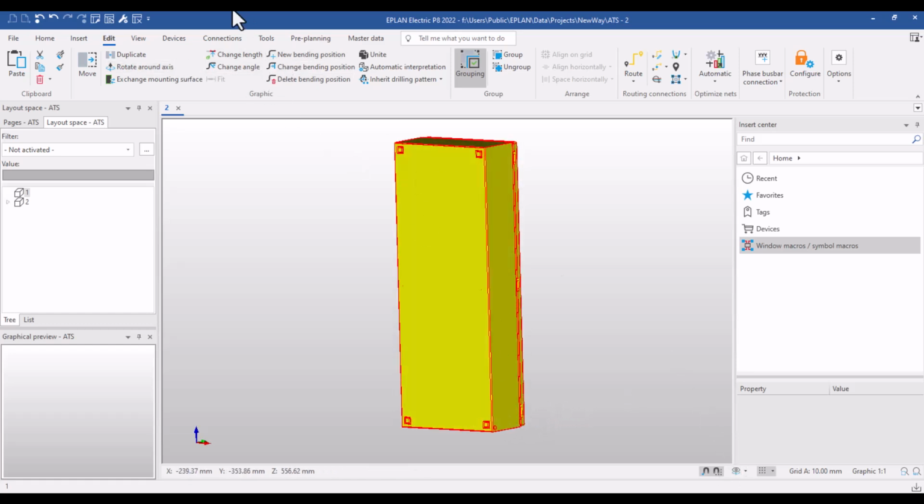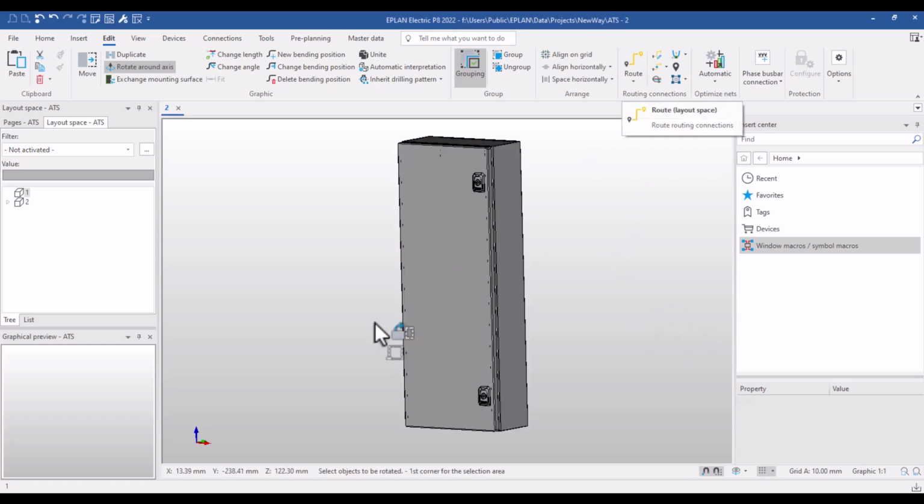After that, I will need to press rotate, select the axis we will need to rotate around. After that, specify the direction of rotation. This is the direction of rotation. We will need to rotate it by 180 degrees. So you can see now it has been rotated in the front view.